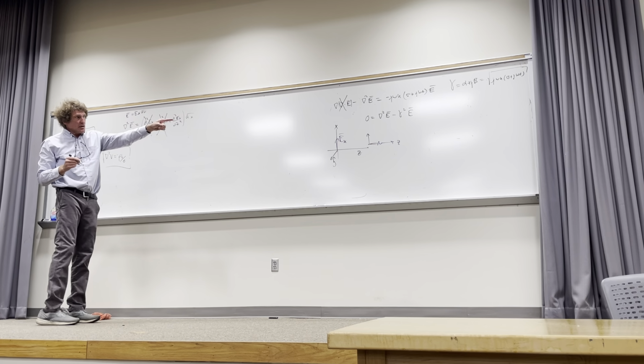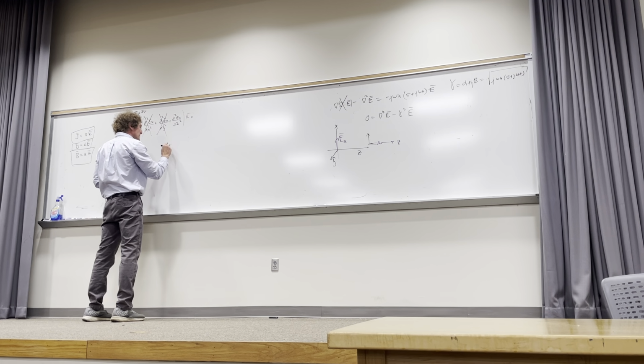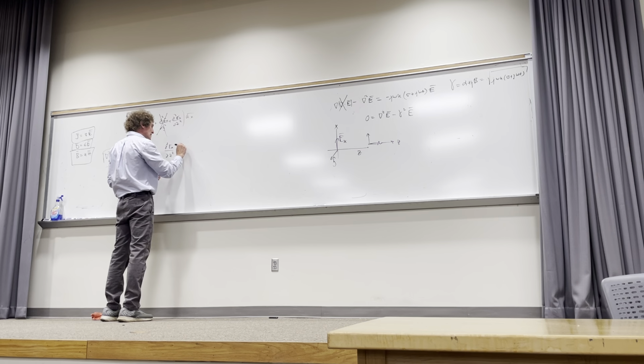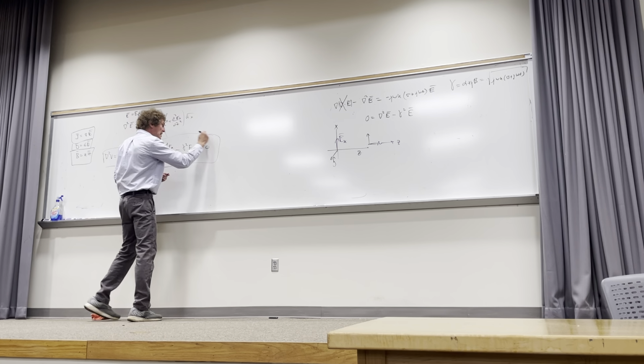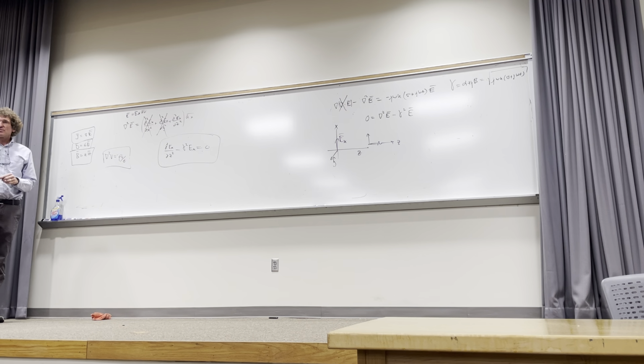So now I go to that del squared equation, and really I just have the second derivative of E_x with respect to z squared, right there, minus gamma squared E_x equals 0. And that is a one-dimensional equation. It's an equation that has only variation in one dimension that represents what the plane wave propagation would be in terms of a differential equation.